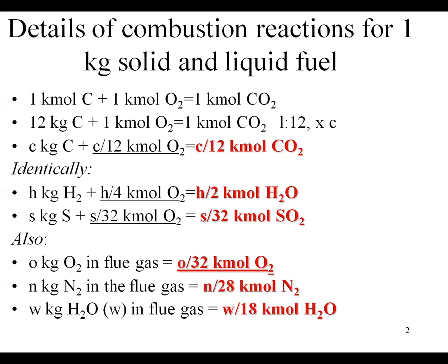Do you know it? Yes, it's 21% oxygen and 79% nitrogen, and others. But when you say 21 and 79, you must say that these are volumetric percentages, because if you are analyzing air as a mass, the figures are 23 and 77. So when you say 21%, you must say percent by volume. Please remember that, because only the good engineers know the difference. Now you know it.